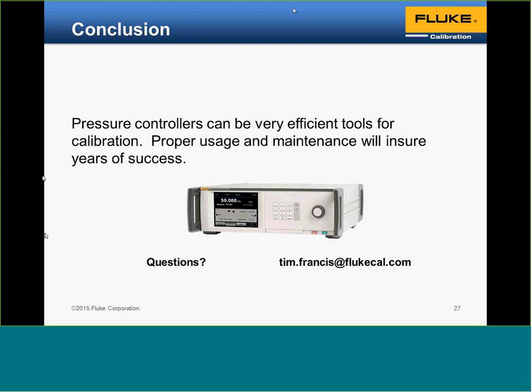Many controllers are sensitive if it's moisture or hydrocarbons or particulates that are in the nitrogen. Again, the user manual of each controller will specify what's required for the supply pressure, and it will provide guidance on the nitrogen that you have in your tank. Most of the time it's going to be what's often referred to as instrument grade nitrogen.